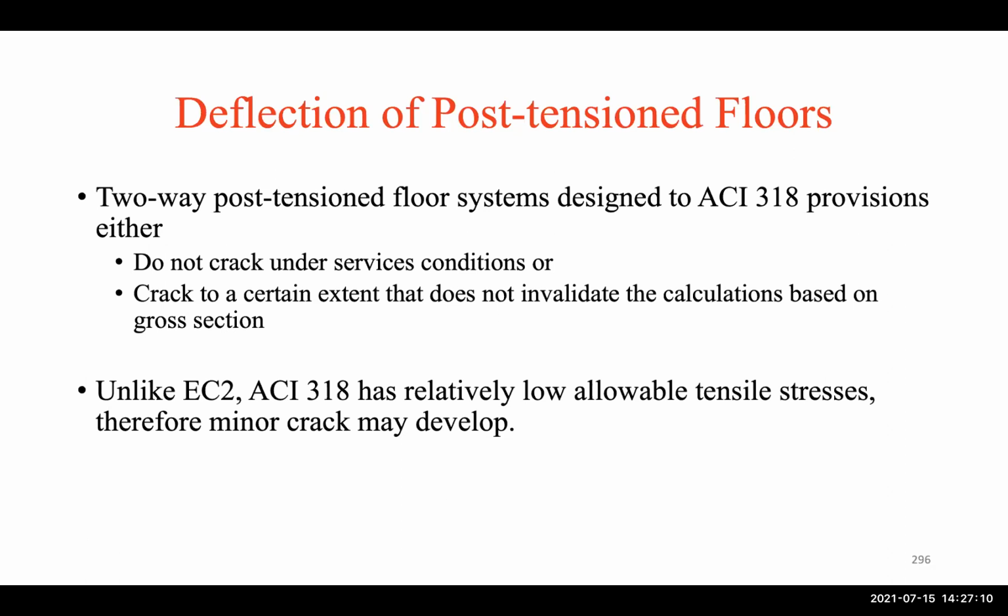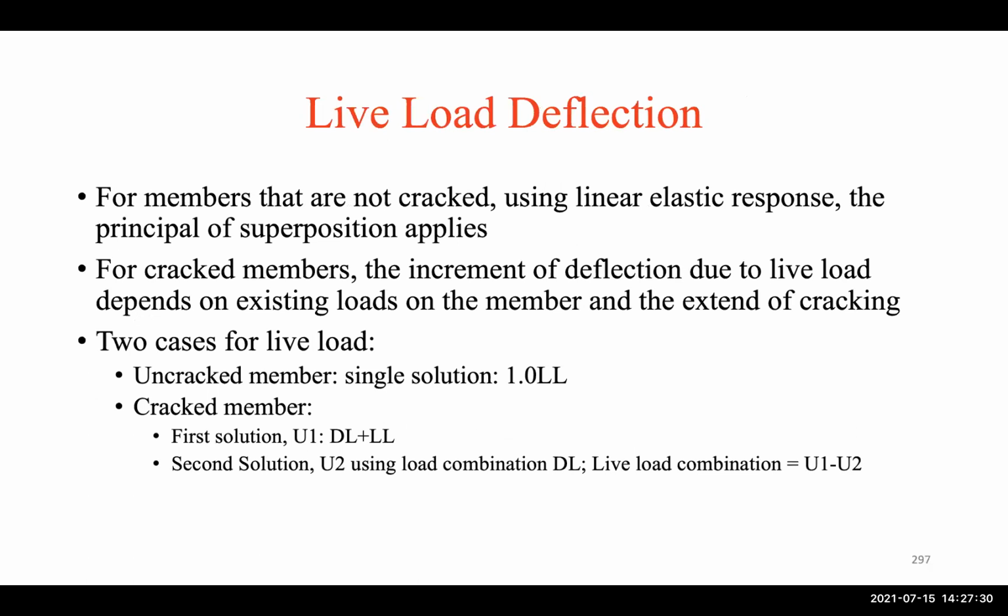Now, since ACI has low allowable tensile stress limits, typically it comes to be like uncracked. So unlike, for example, Eurocode 2 or other codes, we can actually use the uncracked section for that. Okay, so this will be very simple.